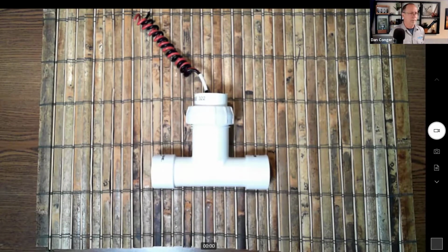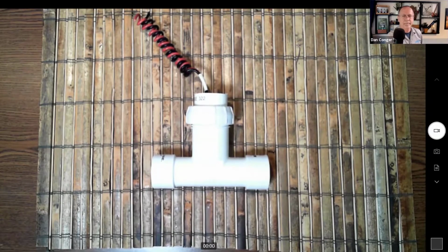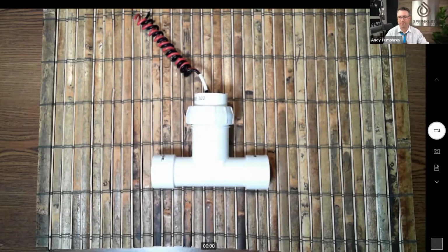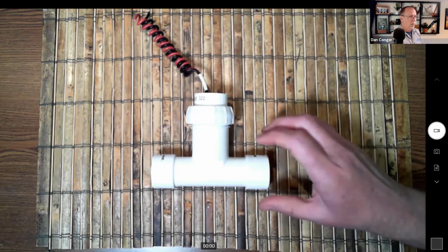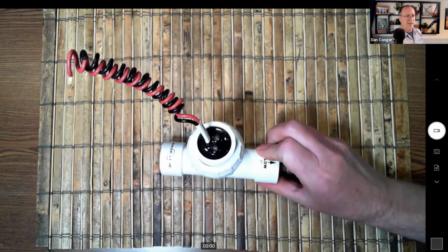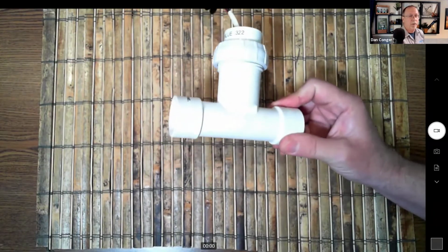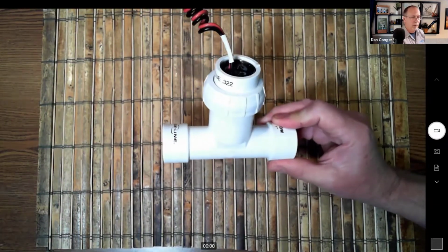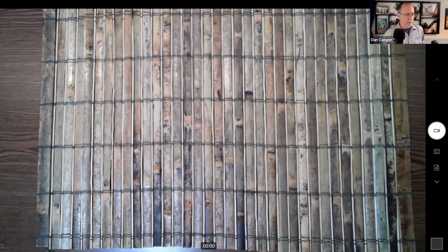Yeah, absolutely. And it's also a function of the pulses per gallon or gallons per pulse, either way. So sometimes you may know what that is. We'll talk about that later. But the K value and the pulses per gallon are inverse or related to each other as well. Correct. Right. So some people just don't like plastic, and I don't see what the big deal about plastic is, but we do have a brass offering in this one. I don't have a brass BFS with me right now, but I do have a brass flow meter, or BFM.